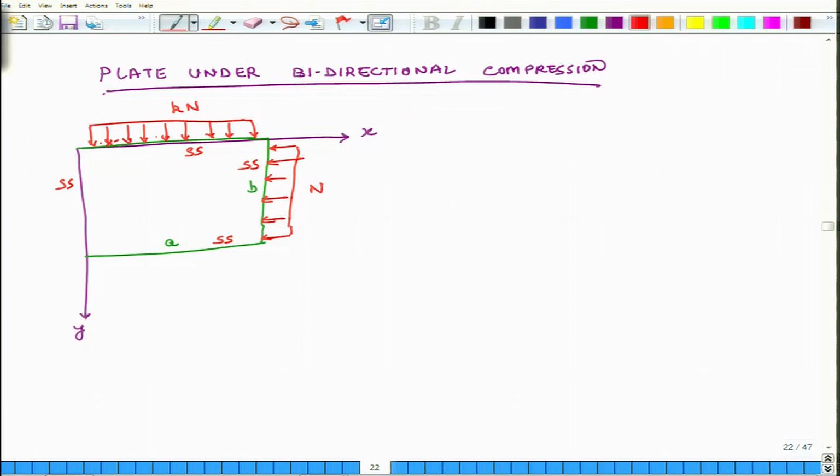Now, we will look at the boundary conditions. When this kind of loading happens, the v displacement is being constrained. So, if I double n, the value of Ny in the other direction will also get doubled. So, this is the type of situation we are trying to simulate. So, the BCs are, let us call these edges: this is edge 1, edge 2, edge 3, edge 4.